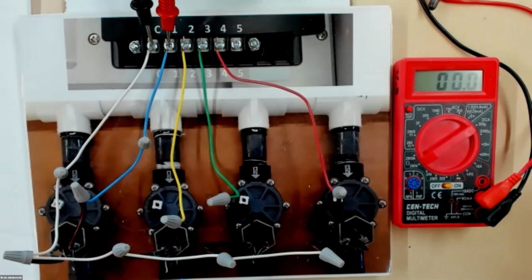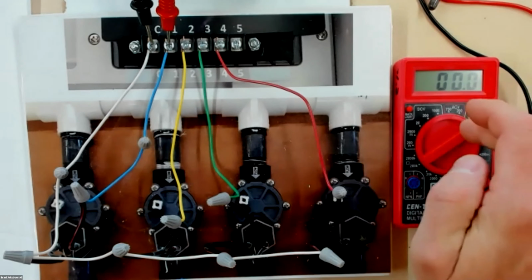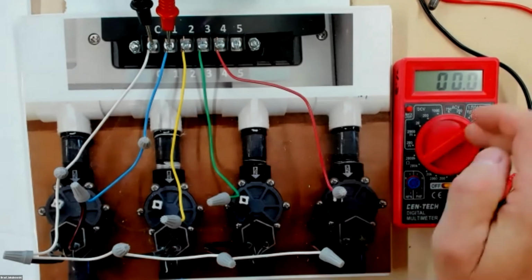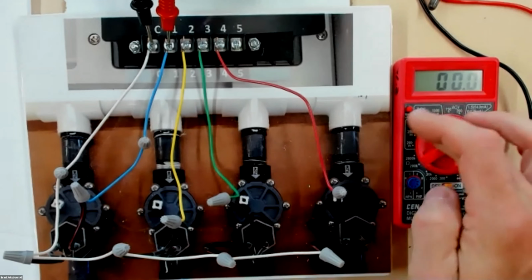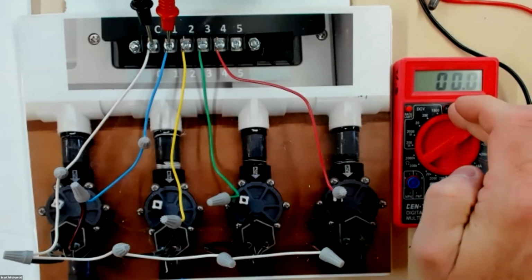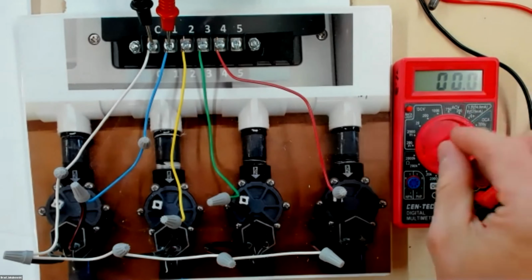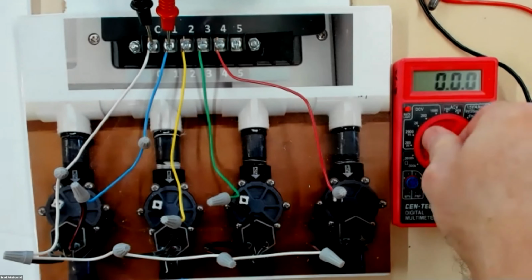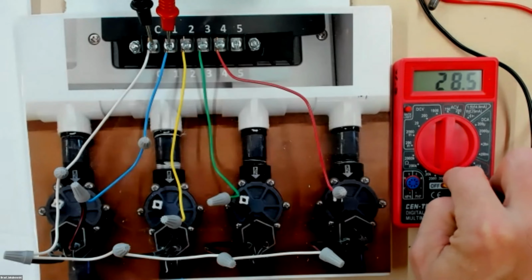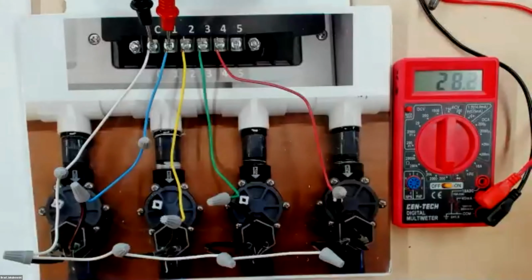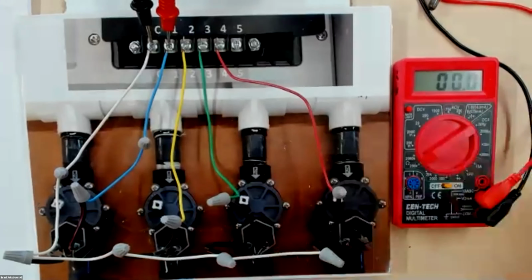So if you have this at its wrong setting, if it's not an auto-ranging multimeter and they still have it set here, they're going to read this as a short, which would then give them the wrong reading. So it's important to make sure that you have this set up correctly, and that you're also reading the correct thing here. That can also give you an oddball reading.